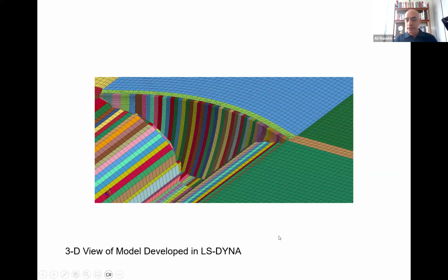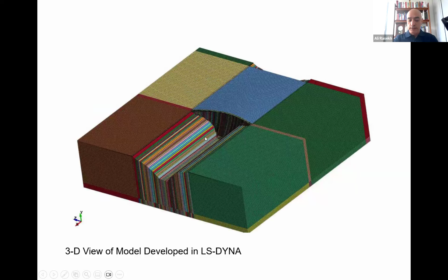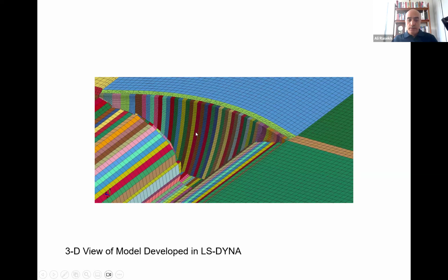Hopefully that helped with clarification. And for analysts, there is friction. We use a frictional interface or frictional contact between these parts on the dam. However, on the foundation side, it is only continuous. There is no separation. It's like the same thing. Blue and green is the same.